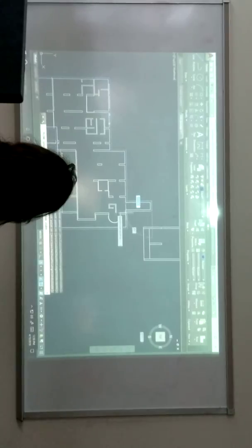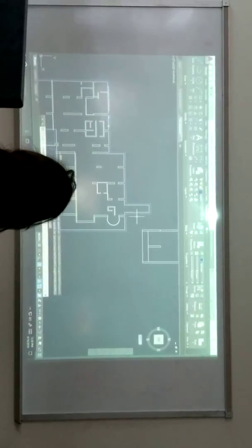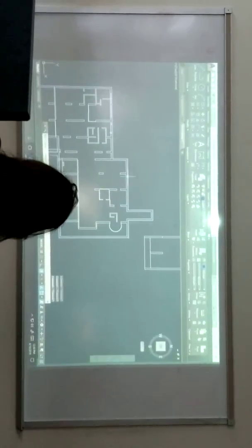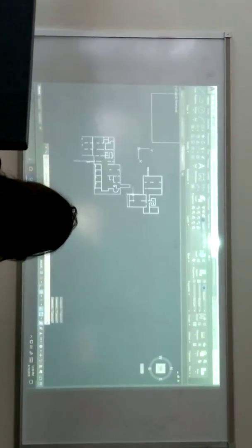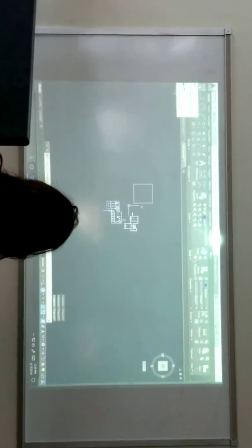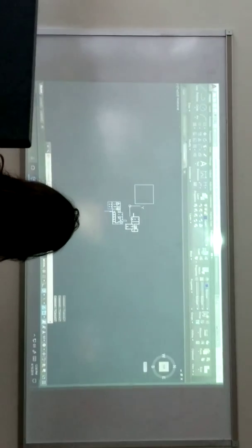If you exploded a polyline, would it just be a regular line? Yes, you can explode the polylines into regular lines. You can join regular lines into polylines. That's not a problem. All right. So once I'm here, then I can just export this, save it as a DWG again, and open it in Illustrator. Okay. So I'm going to do it real quick.